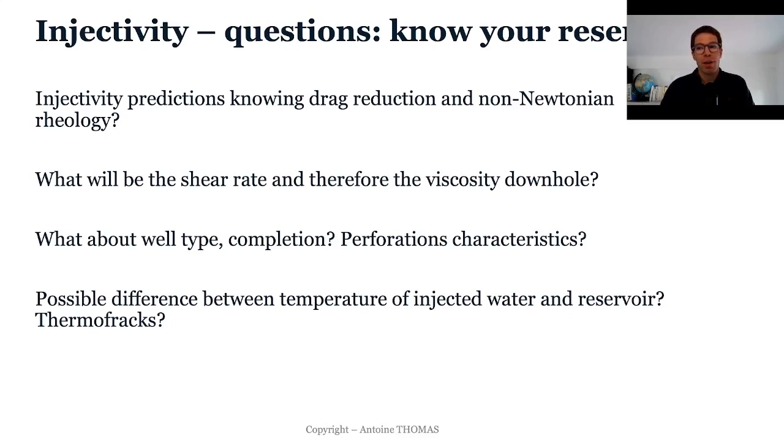But if you have 20 years of injection, and if during summer and winter the water temperature changes, you might be stressing the reservoir and creating micro cracks that in the long term will become bigger cracks. And when you switch to polymer injection, then you have already enhanced the path to the reservoir, which is very important for the polymer itself.